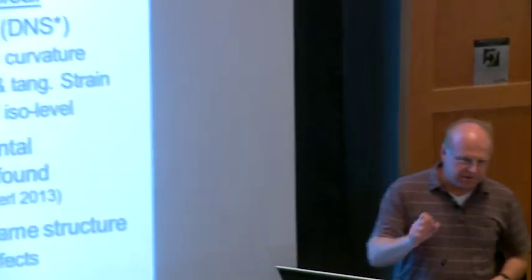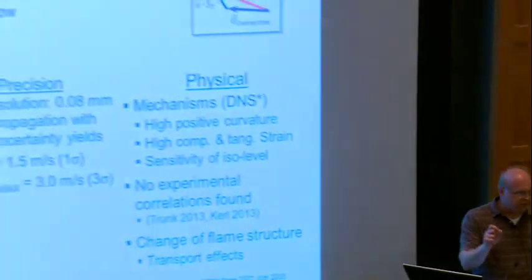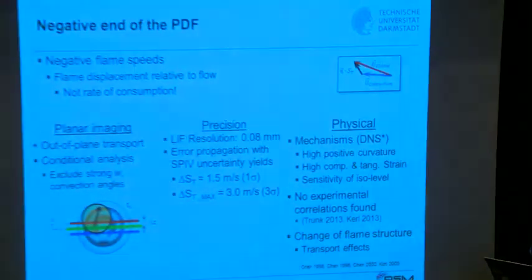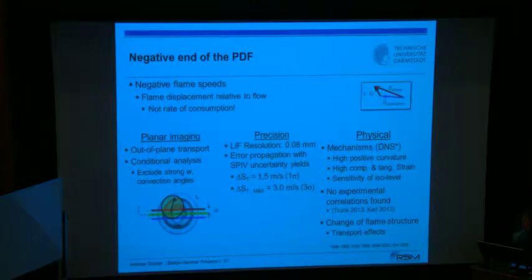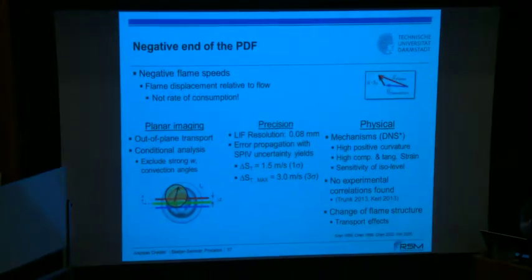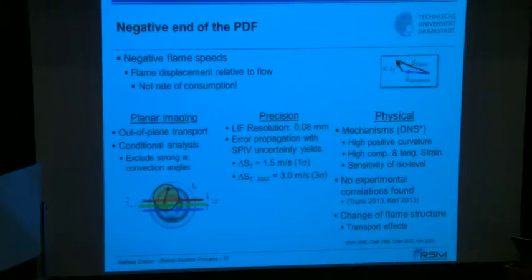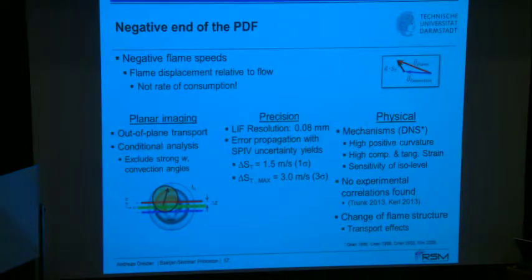And then I don't know for that pressure, but we have looked into that in atmospheric conditions for methane air flames, equivalence ratio 1. That was only 30-40 microns. It is still compared to the displacement where you take the velocity data, maybe only 1/10. And if you have higher pressures, then the distance, because everything gets so steep and small and even thinner, this distance will decrease and is maybe then below the resolution limit we anyway have.